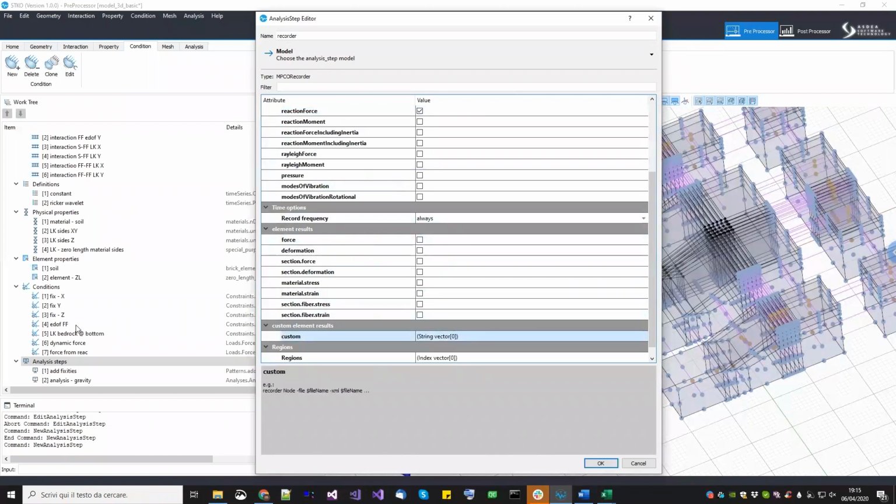Now, since this is typically to visualize the stress in a solid element, you can select the material dot stress keywords here. But unfortunately, the single point constraint does not follow the same rules followed by any other solid element in OpenSees. So they do not accept the material keyword. This is because they just have one integration point, so they decided not to use this keyword. But in this case, there is no problem.